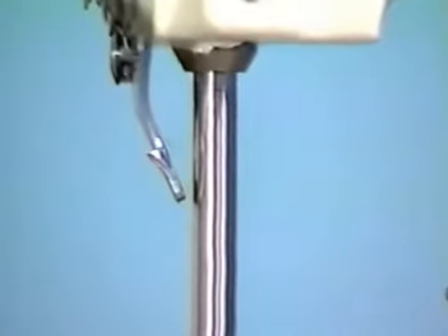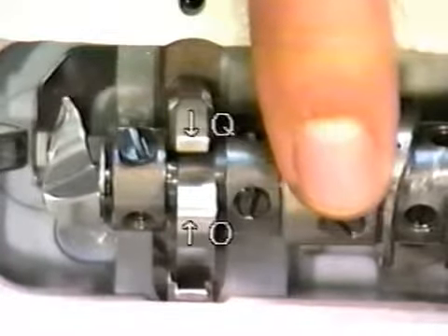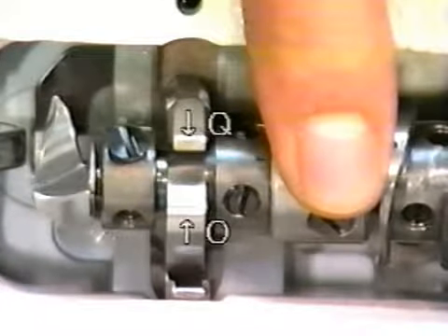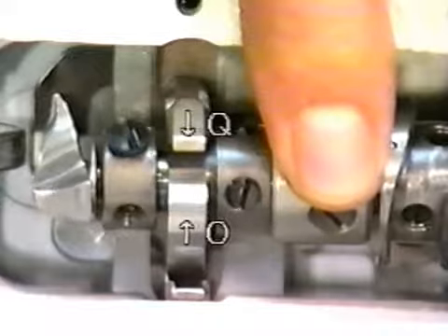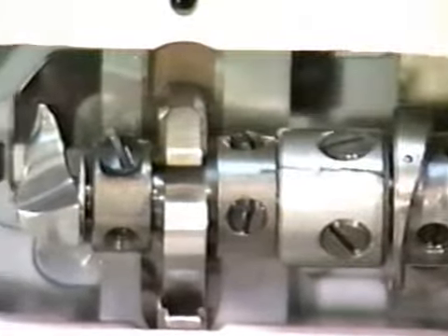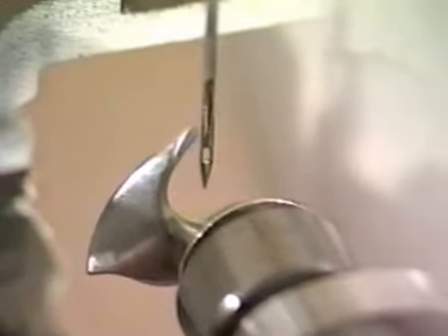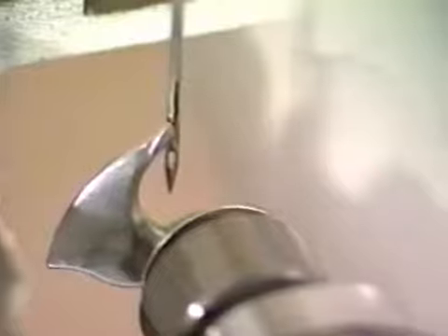Turn the pulley until the lower marker line on the needle bar is aligned with the bottom end face of the needle bar lower bushing. At this time, align yoke slide triangular cam O with the center of yoke slide positioning finger Q. Now, adjust so that the blade point of the hook meets the center of the needle marked by the arrow by moving looper mounting shaft R.